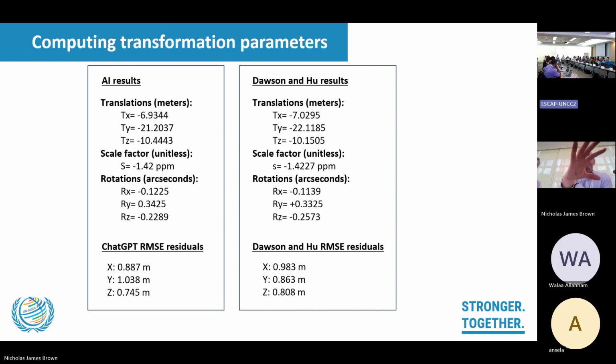I would also think about what you're moving from. If it's from an ITRF to an ITRF, you'd probably be safe. But would that still be the case if you're moving off something that potentially has a geoid ellipsoid separation that's different by 20 meters? Is it still going to iterate in on the final solution? I think if it's small, you can assume it's 0 because you've got iterations. But if it's big, it may be the cause of the residuals that you're seeing. Because if you're using a spheroid that's in a very different position, like the old AGD 66, which is not geocentric, you may cause problems. But I think in your case in Singapore, you're going from an ITRF to an ITRF.